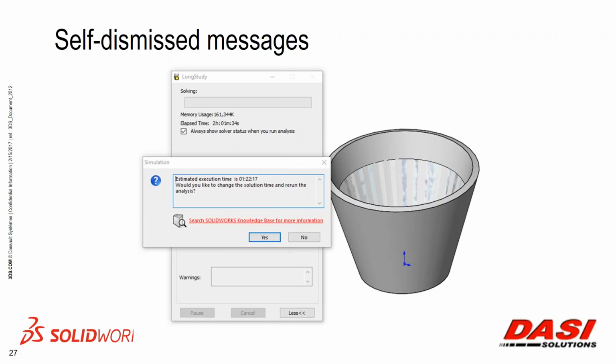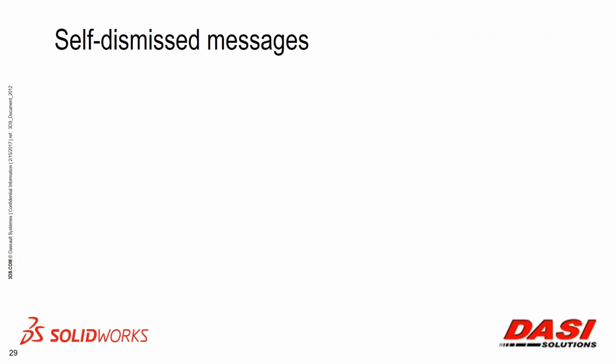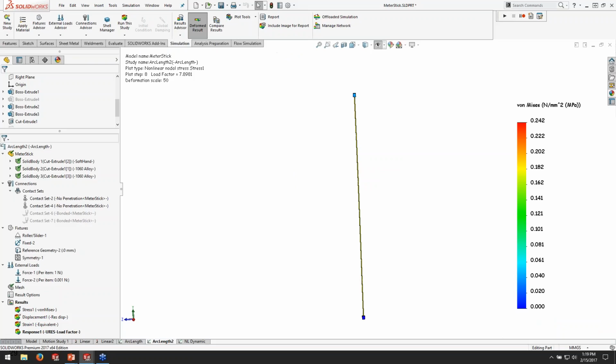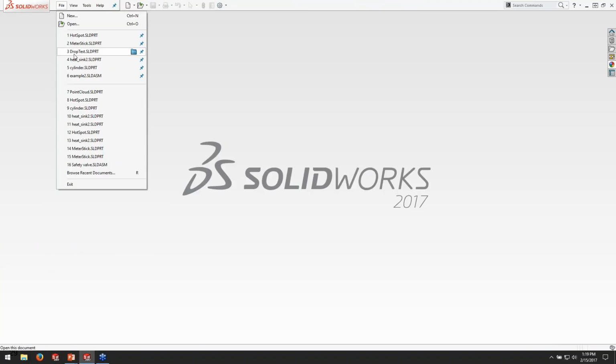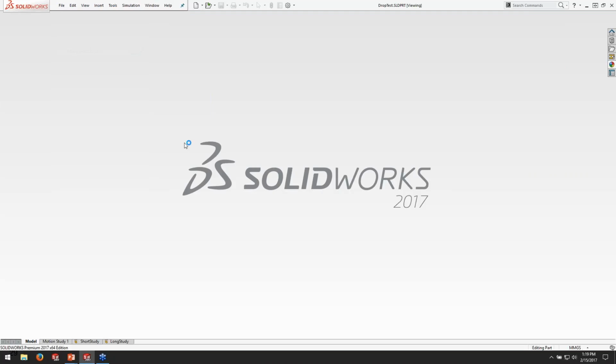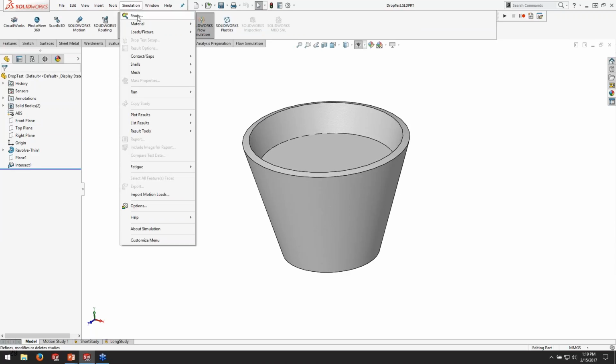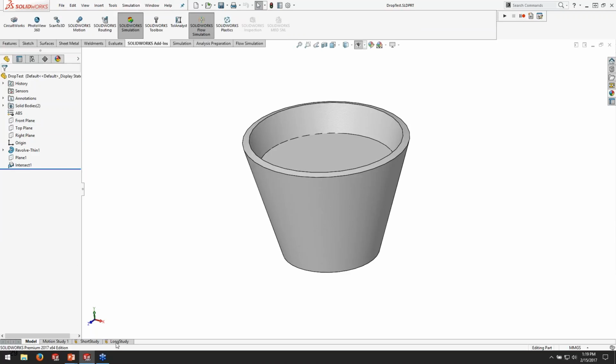Okay, so had it just automatically dismissed the message, it would have been done ages ago. I mean, it says it would have taken an hour and 20, and I've already waited 2 hours, and it's still not done because of this message. So what I'd like to do is just show you where this option is at, so you can turn this on. Because from my testing, it looks like it's factory default. This auto dismiss messages option I'm going to show you is turned off. So you may want to jot this down, or they do also have it in the what's new document.